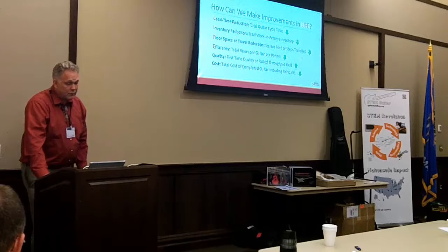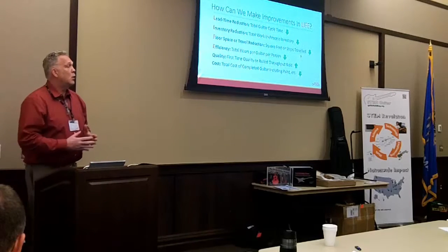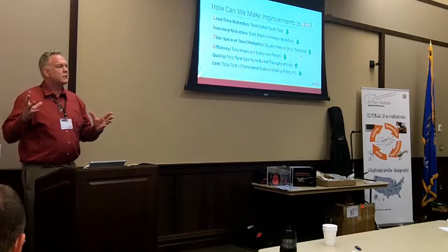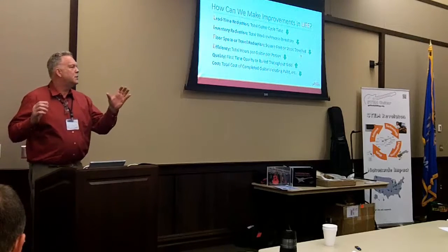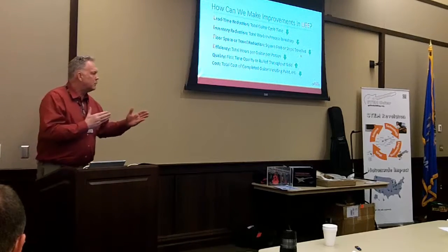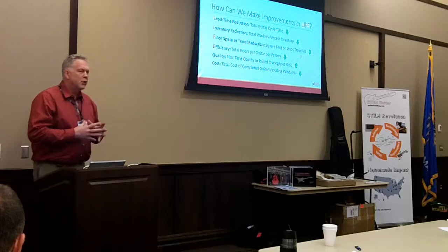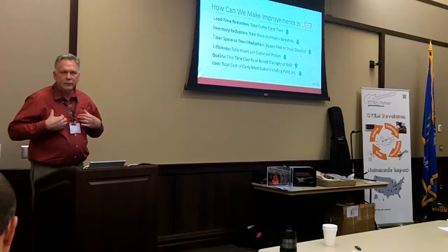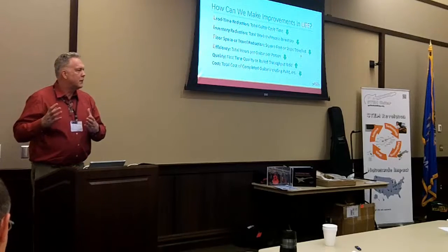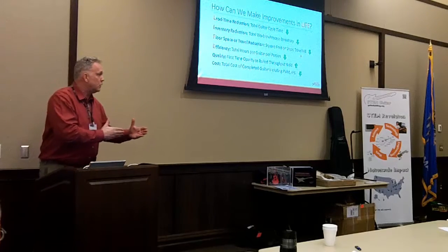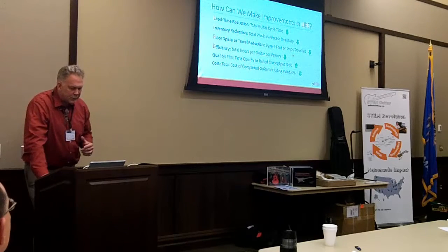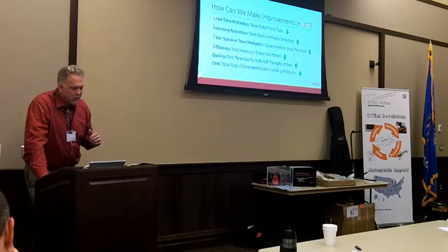Reduce the square feet of floor space. Normally in a production situation, we balance a line and all of you would be sitting on a line doing one product and passing to the next person. Well, nobody wants a guitar that was built by the whole group. They want to build their own guitars. So the way we built it was so that you just go from station to station with your guitar and neck until you finish the process. But everything you need is there at the station. And we want as few steps as possible.